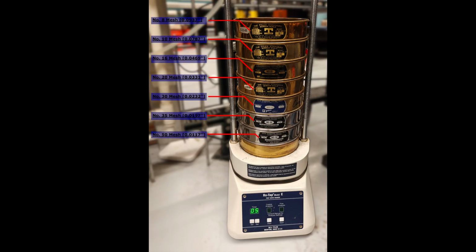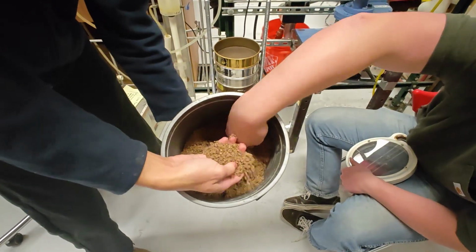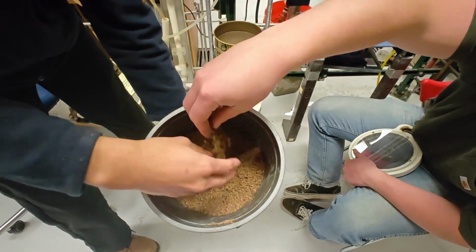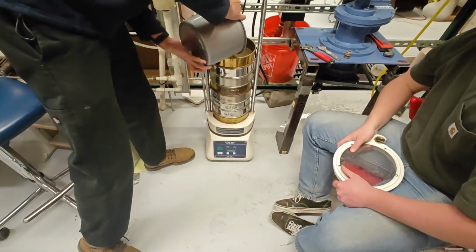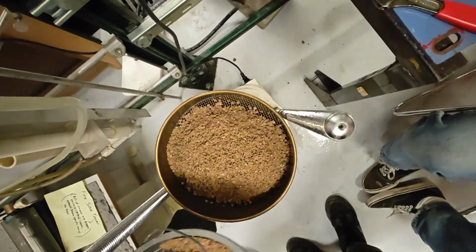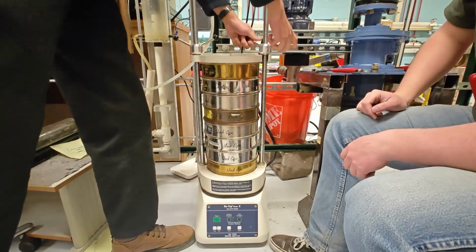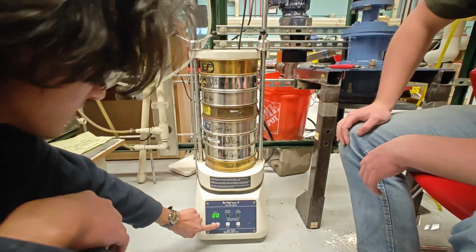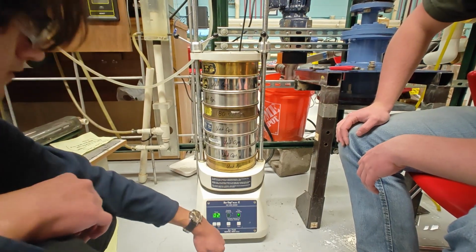The sieve tower we chose is lying on an auto siever that vibrates the tower to filter out the particles that were collected during the previous steps. So dry. All dry. By running the collected solids through various mesh sizes, we can determine the particle size distribution. During operation, the sieve gently shakes, allowing particles to fall through the appropriate meshes.